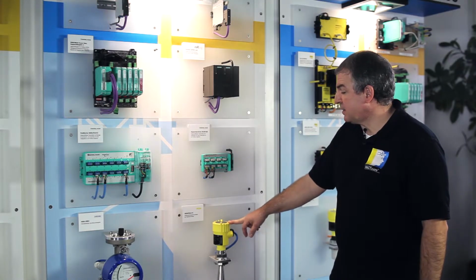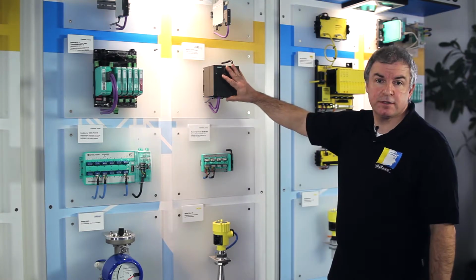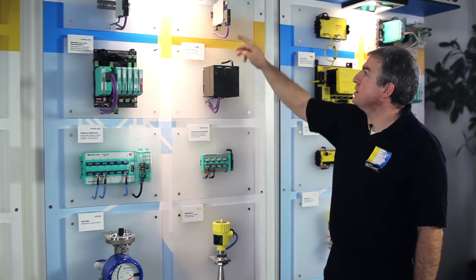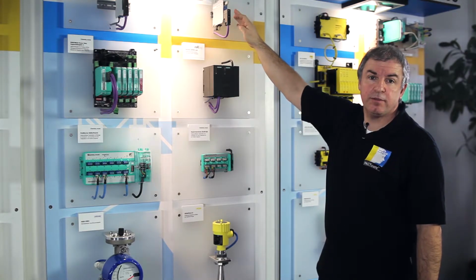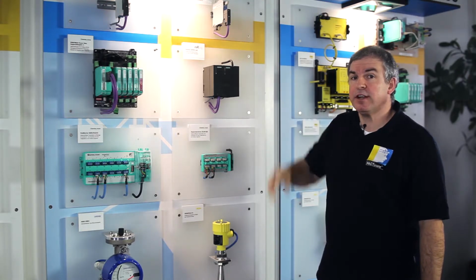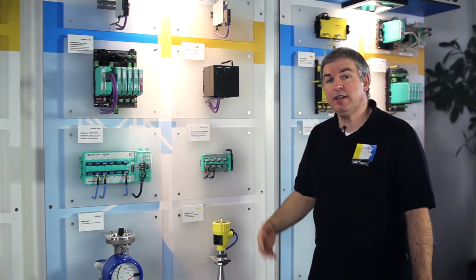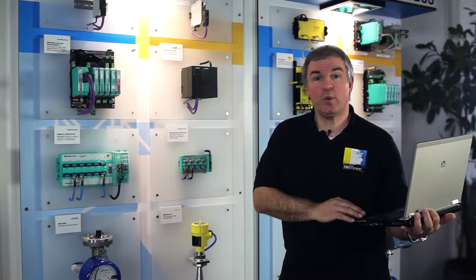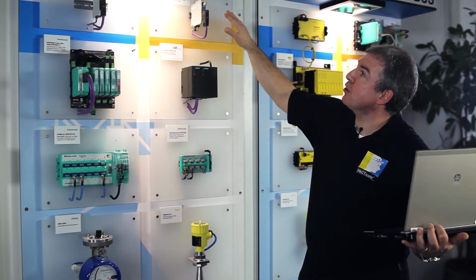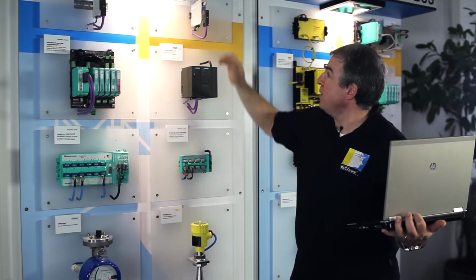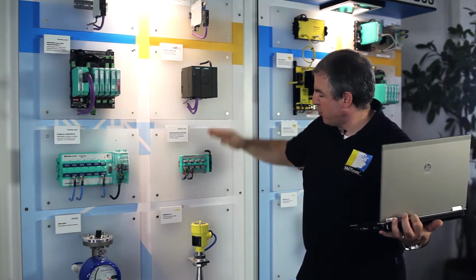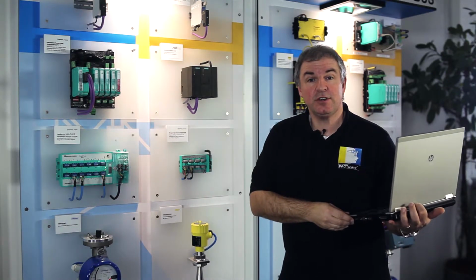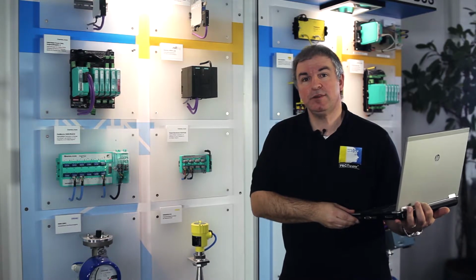The radar level sensor is connected to a Profibus segment coupler, which is running Profibus DP, which is then connected to the Ethernet network by using a gateway. The PC is connected on Ethernet. That means with PACTware you have easy and complete access to your sensor. The laptop is connected via wireless LAN to the Ethernet network of the PACTware demo wall. From there we go via Profibus DP and Profibus PA to the sensor. The remote access to the sensor via PACTware is now possible.